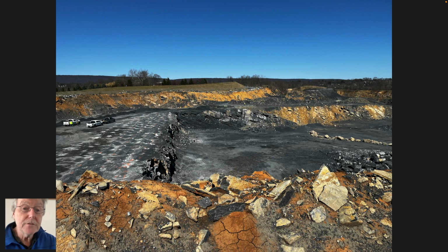This is a limestone quarry. If you look on here, this is a bench with all the, these little white points are drill holes, which are drilled as blast holes. Each of these drill holes is filled with ANFO, ammonium nitrate and fuel oil, and then stemmed in to seal the tops, with detonators put in them. These are used to blast the bench. This bench here is missing and has been blasted.